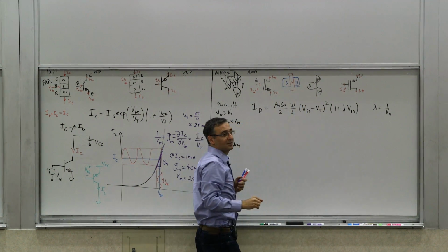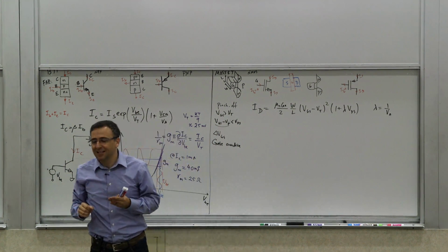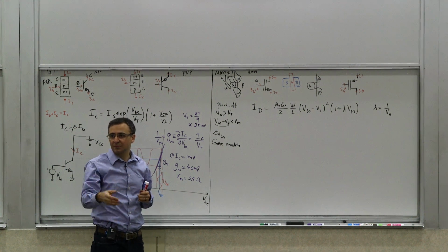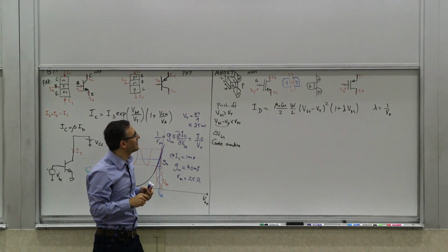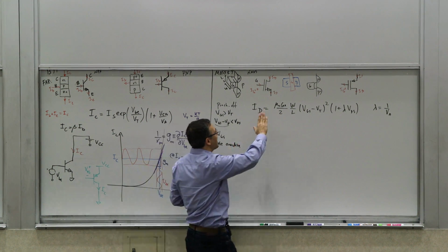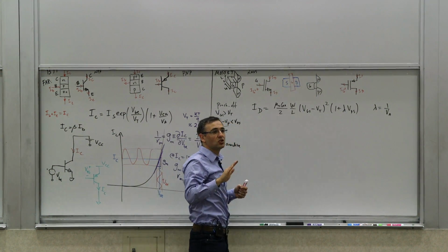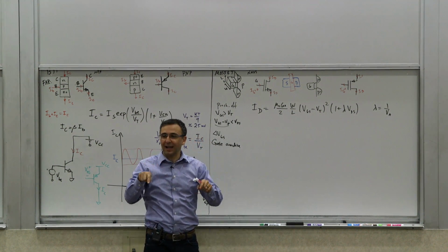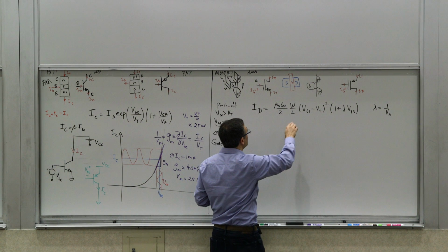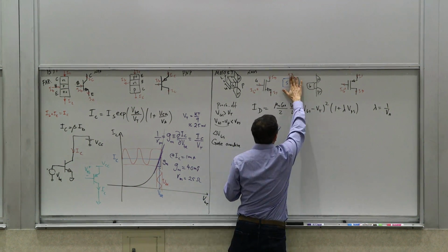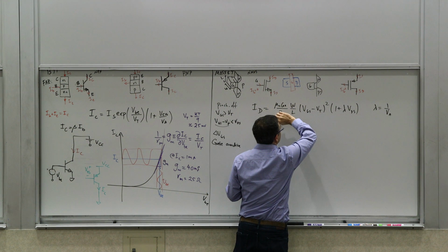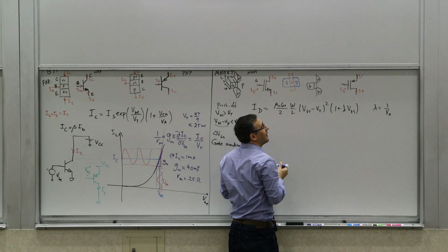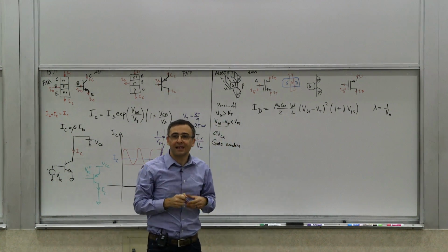First of all, drawing it that way is harder. But more importantly, the way the transistor is built is that there are different masks, and we'll discuss that slightly later. Often the gate is used as a mask for making the drain and source. Whatever implant you do to make the drain and source high density, you do to the gate too, but the gate blocks it. So effectively, these parts don't get the same doping that these get. Practically, the mask looks like that, so the transistor in the layout looks like that.